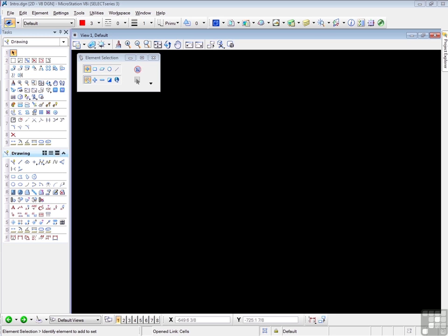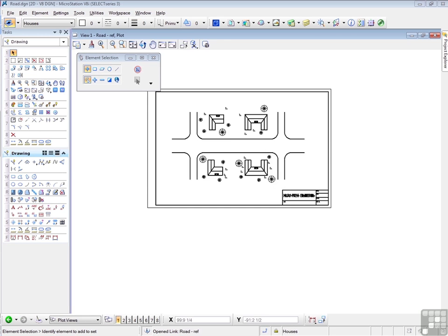But let me show you some of the more important subjects that will be covered. First, in the 600 video set, you will look at the extremely important subject of references, where you link saved views, models, and other design files to the current design file. This is very important since it's used in all production work, large or small. Linking design files to themselves or to other outside design files provides a very effective method of accessing and updating information between files.